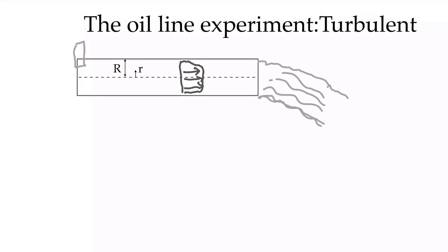And we'll see this when we come to see how we do our calculations, that there is this region of overlap where we could have laminar or turbulent flow, and it's of course not a place where you often want to be working. And the safest assumption as an engineer is that there will be enough disturbances, there will be a disturbance to be amplified, and the flow will be turbulent. So we will very often say transition occurs at a Reynolds number of 2300. In subsequent videos, we're going to look at how to do calculations to calculate the pressure drop.